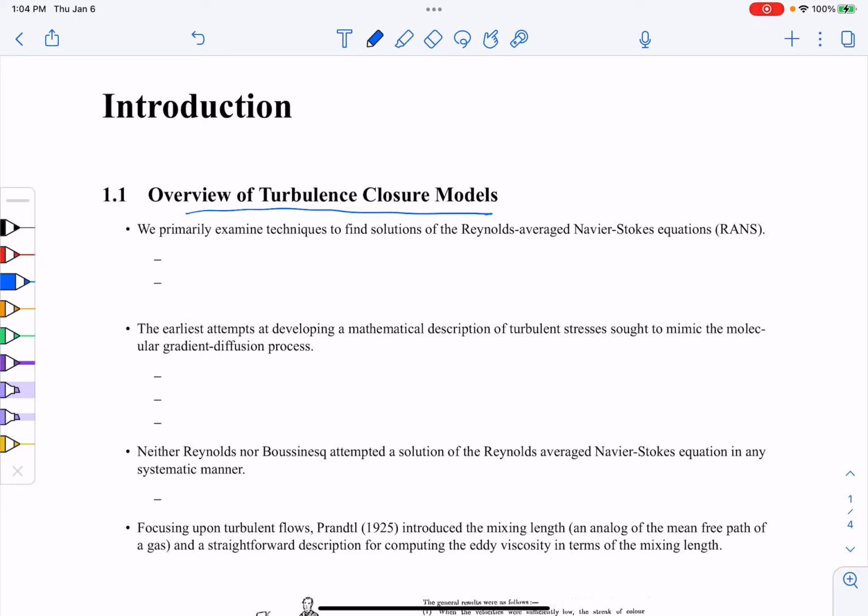And the majority of this turbulence modeling world revolves around this word right here, Reynolds average Navier-Stokes. And Reynolds averaging, which we'll show later, is nothing but something like U equals U bar plus U prime. And this could be any variable. This is a velocity component. Here, U bar is nothing but the average variable. So you would take like a time average, and the prime is the fluctuating variable.